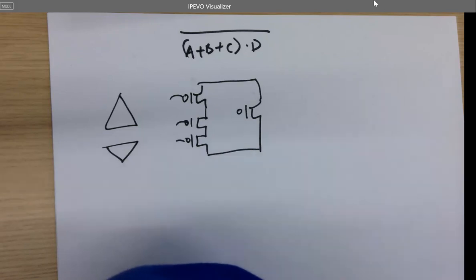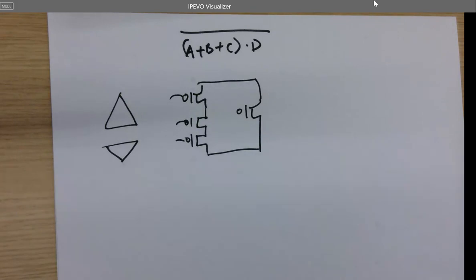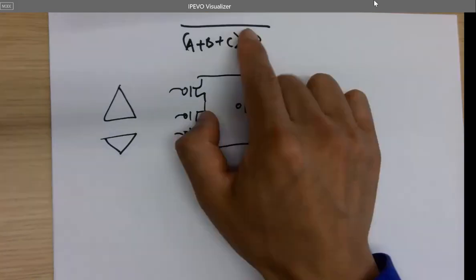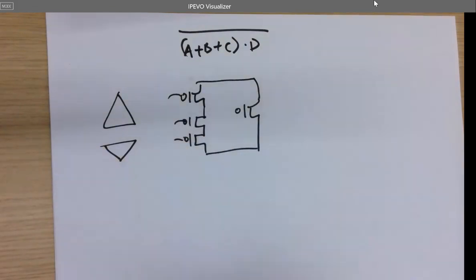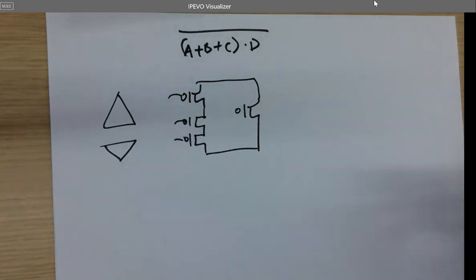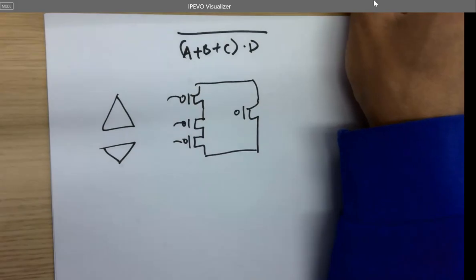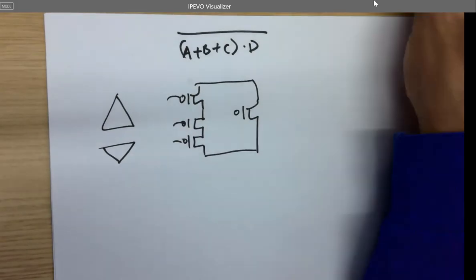You have the gate level circuit. That's a gate level. So we're doing the AOI logic, right? This is pretty much the gate level because these are individual. These PMOS are right on the top. So who can do the NMOS at the bottom?